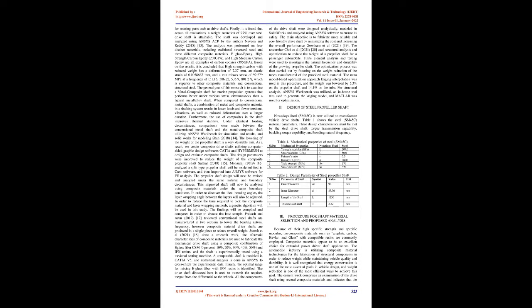The propeller shaft was studied utilizing FEM methods for an accurate design solution, Ansys package. FEM 3D shell 99 element and solid 46 layered element was used to simulate the propeller shaft. All failure modes were investigated, as well as linear static analysis, vibration eigenvalue analysis, buckling analysis, and harmonic analysis.